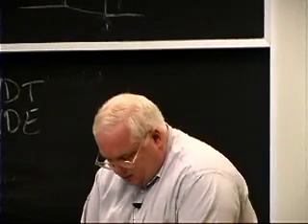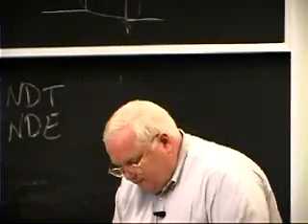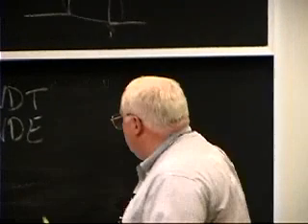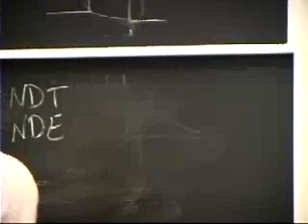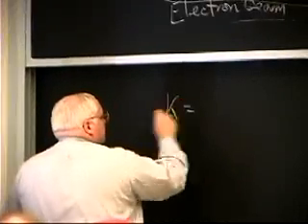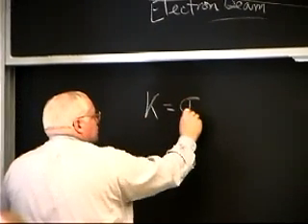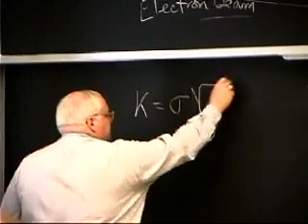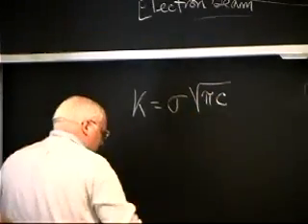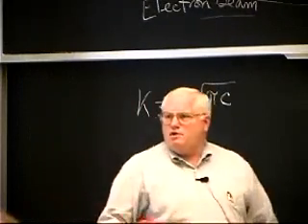And if we go back to our fracture mechanics, the strength of a structure is not related to the stress. It's equal to the stress intensity, which is equal to the stress times the square root of pi times the crack length, or the flaw size.